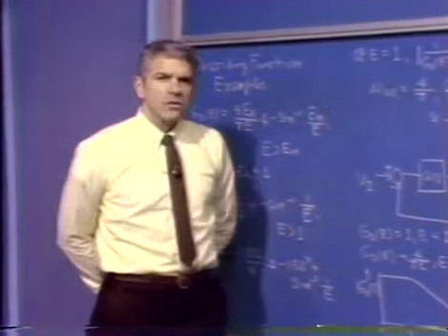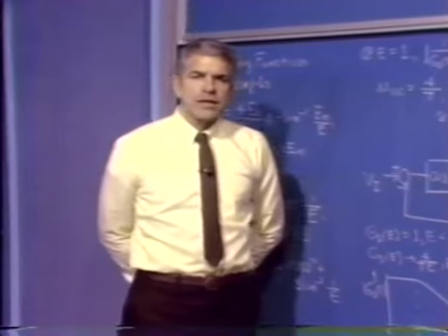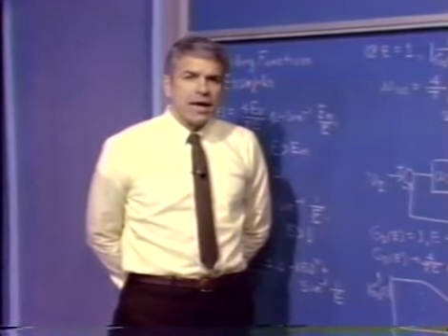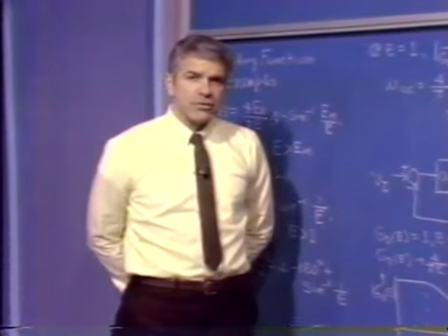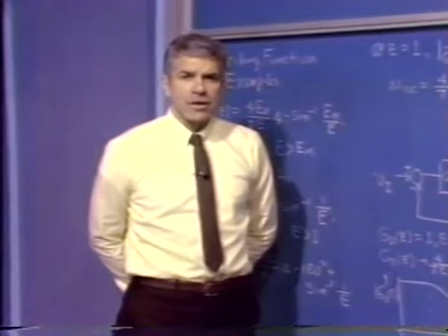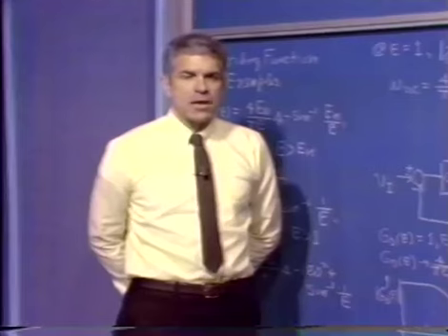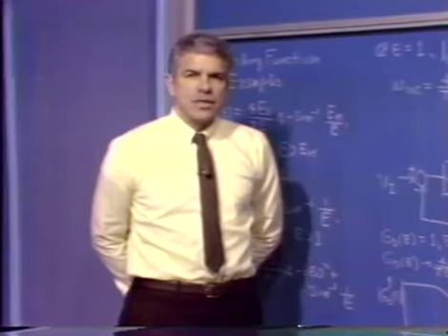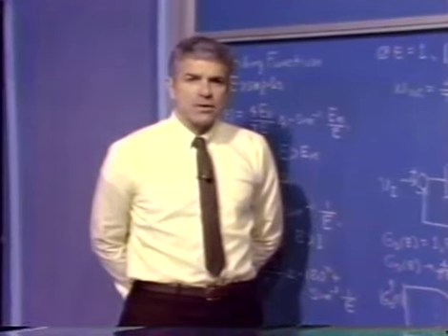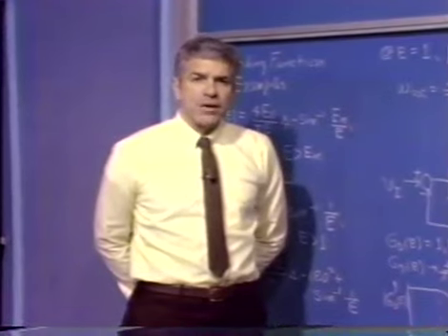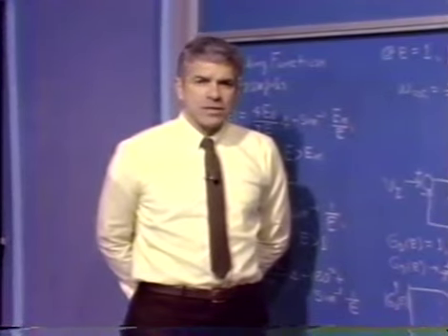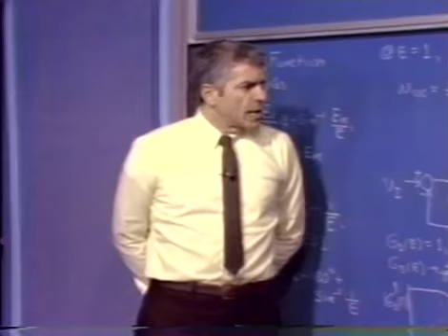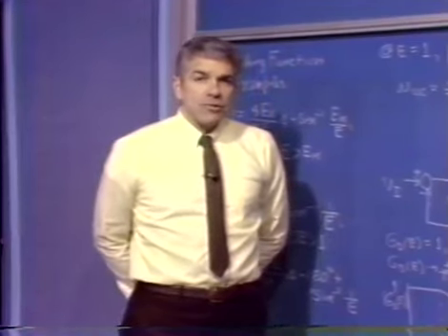We can also look at the amplitude. We recognize, of course, that the actual signal at the input to the nonlinear element, which is where our describing function analysis tells us amplitude, is a triangular wave with a peak value of 1 for our normalized system. Our analysis tells us that E should be equal to 1.